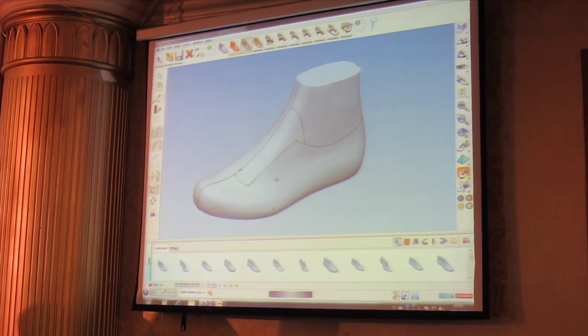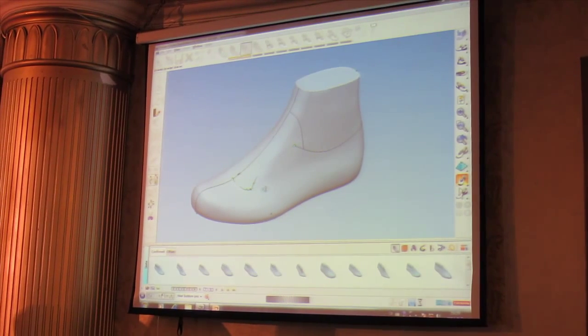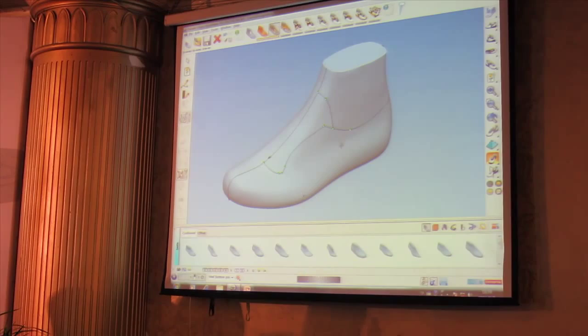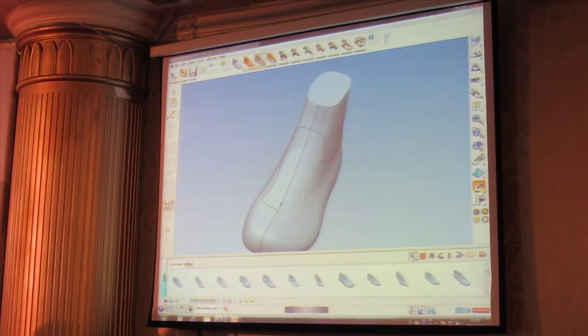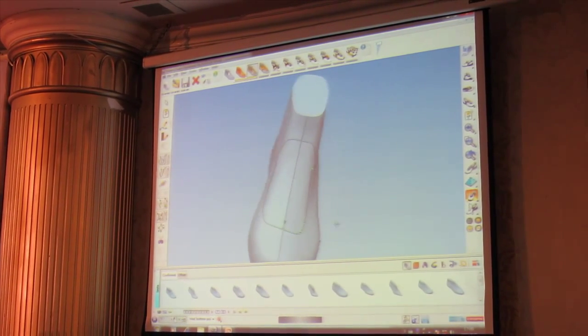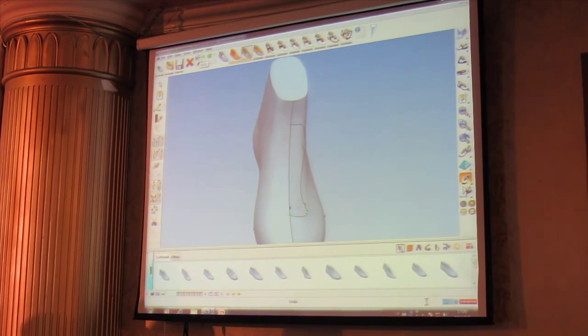Once I've sketched curves, I can edit them, so I can pull the points around and make changes to the points if I wish to. I can also select all those curves and make a mirror to the opposite side. This mirror is a linked mirror, meaning that if I change one side, the other side will automatically update. Okay? If I undo and redo that.